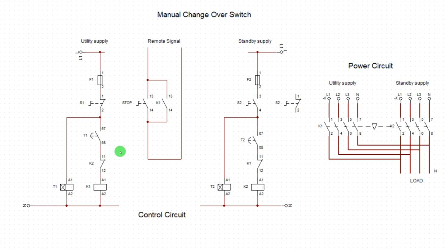Otherwise, if here is closed, both of them will come up at the same time. And both of them are using the same timing. So in that case, both of them will close, and I don't want that. So that is why I swap this. Okay, so that we use open, but in real connection, you're going to use close. I hope you get the gist now. All right, now I want to simulate the mains so that you see how the remote signal will take effect on the genset position. Let's do that.